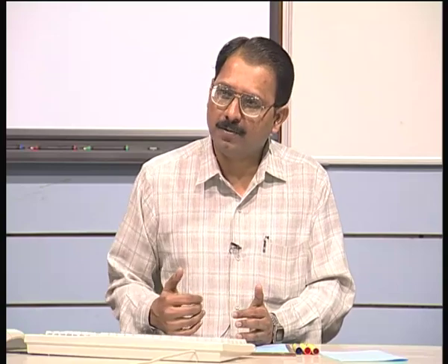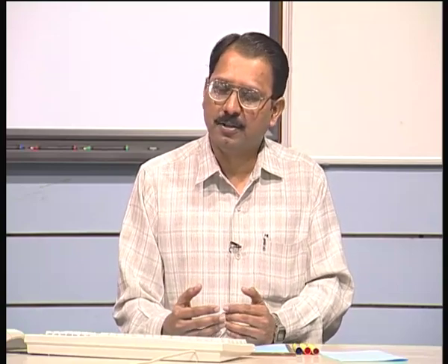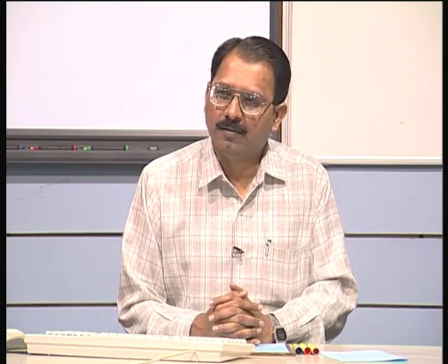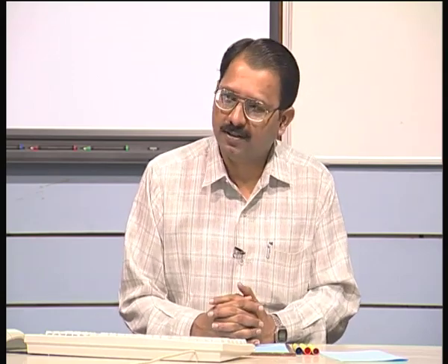Collisions come when one object is moving in a space relative to the other. I know the sweep representation of a solid, I can convert it into octree or voxel and quickly check whether any collisions are happening. Like in many robotics and machine tool simulations, you need to check for collisions. So, one can build volumetric simulation based on octrees to quickly calculate this kind of situation.